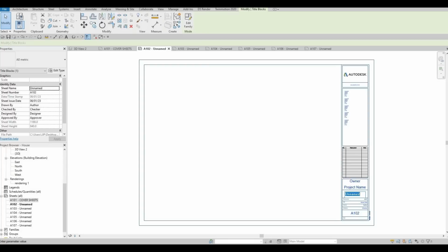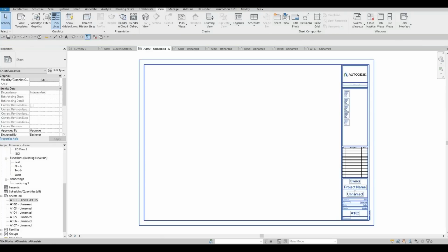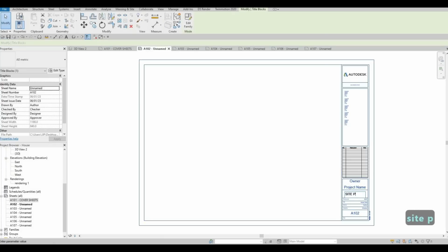So this one we're gonna put site plan. Next, you could go right here as well. This one should be after site plan. So here we did site plan, and then we have our first floor, and then here you could put the owner. So ACD, so Archcore Design, and then project is whatever house you want to name this one.